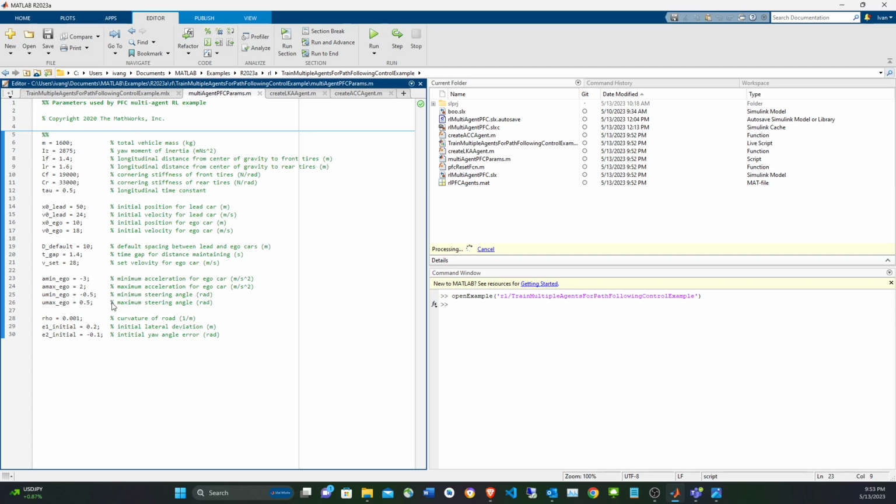So the acceleration is going to be a continuous domain for the action, while the steering, we keep it as a discrete domain. So we have radians. The steering is going to go from -0.5 radians to positive 0.5, but since we're going to use a DQN for the steering, it has to have a discrete domain, so we divide that domain by 32 chunks, 32 elements, so that's how we make it discrete. But in the case for the acceleration, we're going to use a DDPG agent, which can work with continuous acceleration domains, so we keep it continuous.